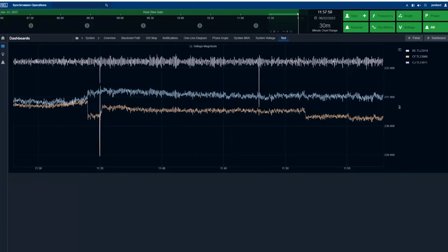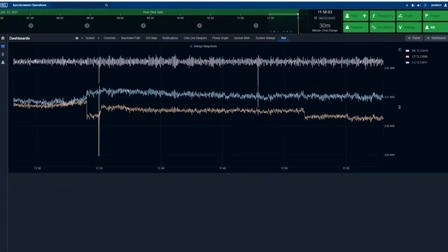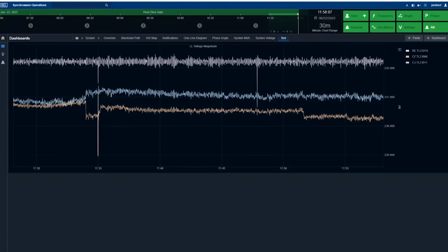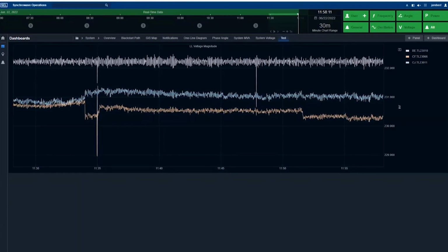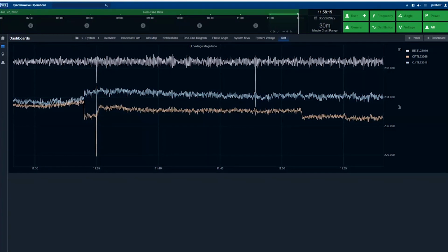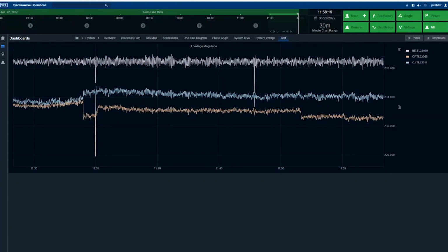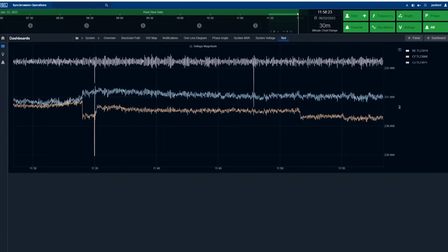The second point I would recommend is installing both voltage and current as a minimum, at any location where you have large generation sources, or large distributed, large DER sources as well, like solar farms, wind farms. We're seeing a lot of dynamics based on those, and as an industry, we just have so much to learn in that area, and I think having this data is going to provide you a lot of value from those specific sites.